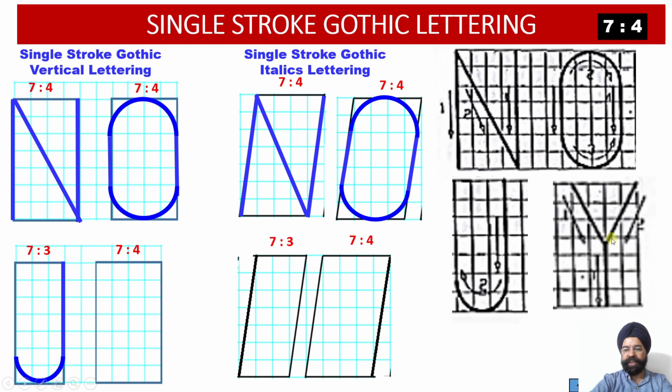Then another alphabet which we are going to draw is Y. So Y, you can see this is one dot reference point, second dot reference point, and 1, 2, 3 blocks from the top after 2 blocks. So 2 blocks is my width, and then I will join this. So 3 strokes will be required to complete this alphabet Y. 1, 2 and then 3. So let us see. Oh sorry, before we go, this is my italics J. In the italics J, this vertical line will get inclined and the curve will also be slightly inclined, so that I complete my inclined J.